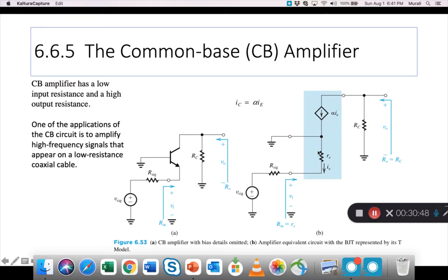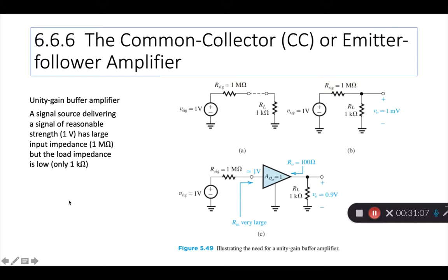So these two parameters appear, and generally you'll notice in the textbook, whenever there is a resistor in the emitter circuit, we switch to a T model. It makes the job easier. Okay? Alright. So using this, some formulas have been derived, which I'm not showing, but they are in the table that I just showed you.